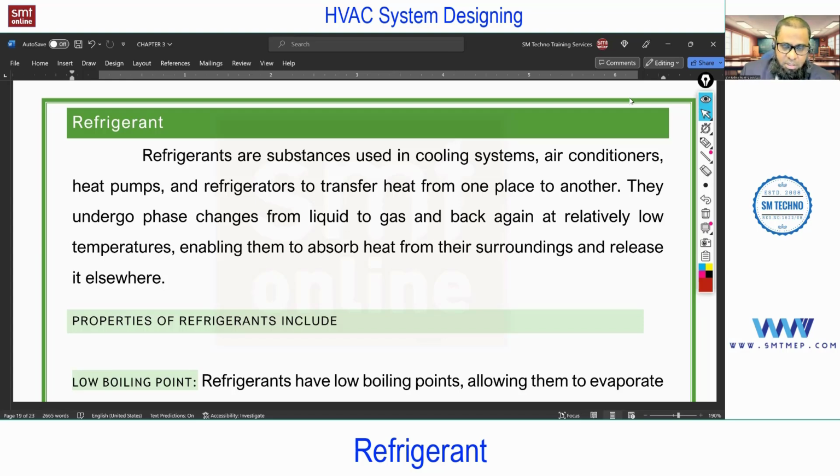So what we discussed till now, those concepts you can find in an animated way in that video, so that we can deal with the vapor compression cycle. So what is refrigerant? In short, I can say it's a heat carrying medium during the cycle. It extracts heat at the evaporator and rejects heat at the condenser.